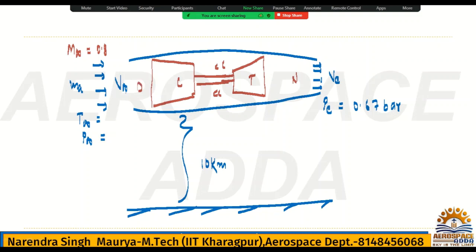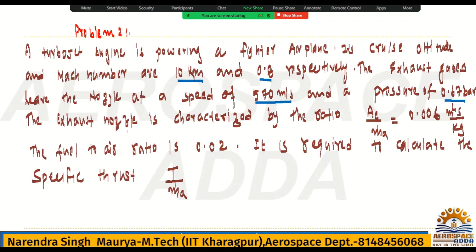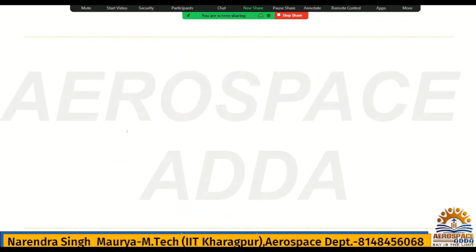Fine. So they are saying calculate specific thrust. Let me first write the thrust formula. The complete formula has momentum thrust and pressure thrust. The thrust is nothing but m dot a times (1 plus f) times (Ve minus V infinity) plus (Pe minus P infinity) into Ae. Yes or no?